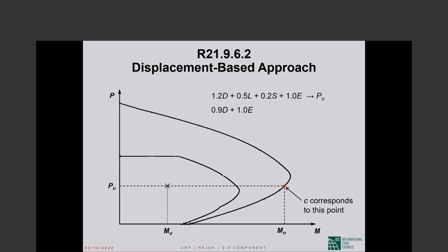Okay. Now, axial load on a shear wall will come from the designed load combinations, and there are only two seismic designed load combinations. We have seen them many times: 1.2 dead, 0.5 live, 0.2 snow, 1.0 E. The snow term is immaterial for you, and 0.9 dead plus 1.0 E. I have described that as the additive load combination, that as the counteractive load combination.